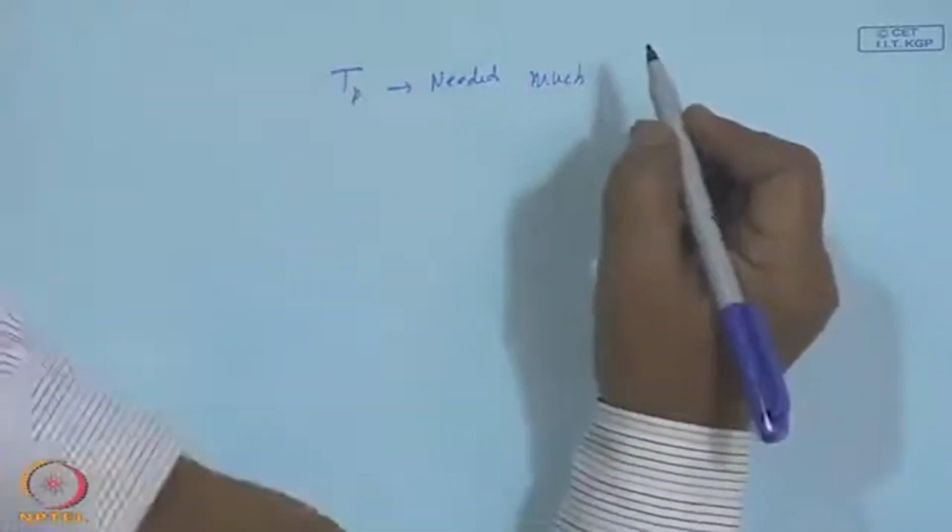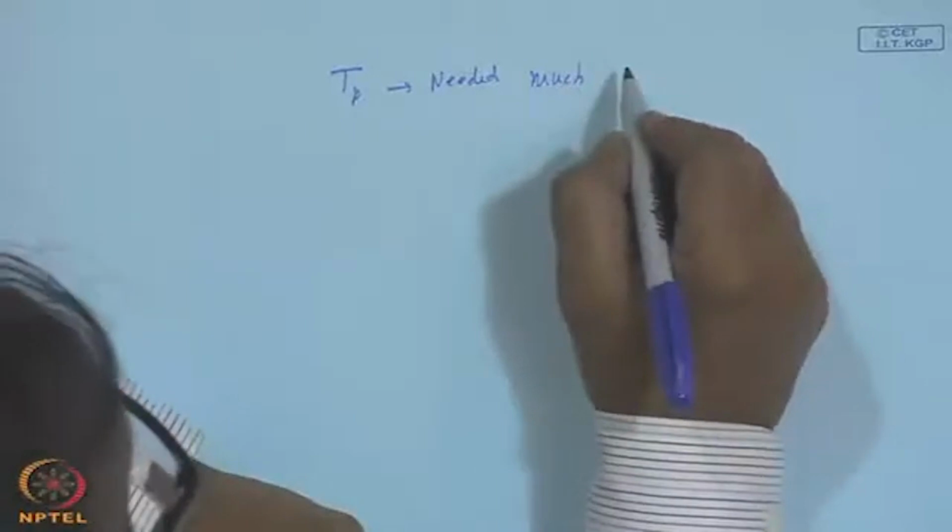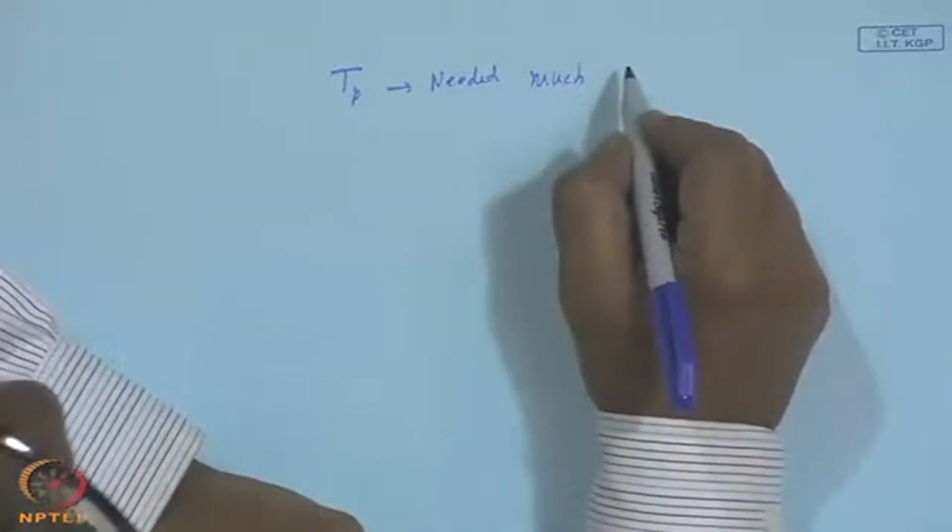If you are comparing an absorber which weighs 10 kilograms to an absorber which weighs 2 kilograms, with, let us say, specific heats being almost the same, or half, or whatever the ratio, MCP ratios. Now, if you have got an MCP 10 times that of the other MCP, then the energy required to heat the absorber to the desired temperature to deliver energy at the desired temperature will be much larger.